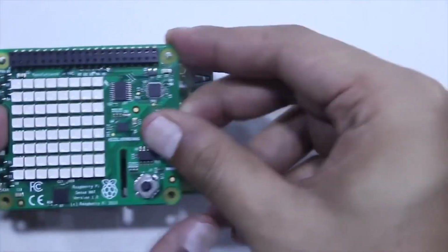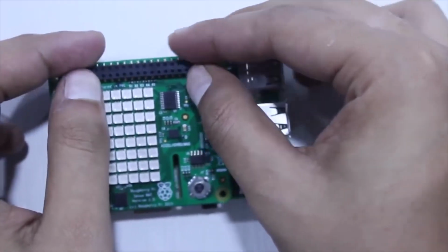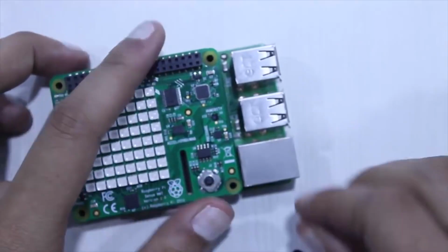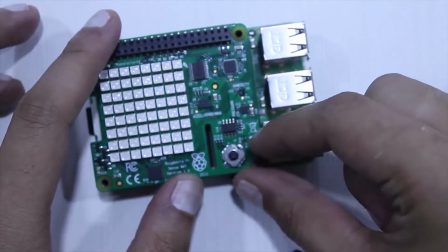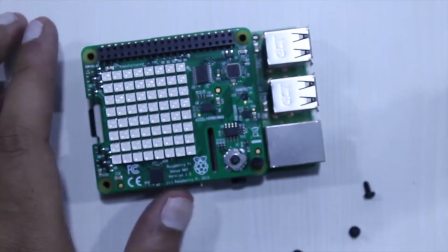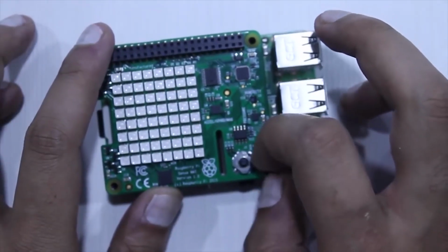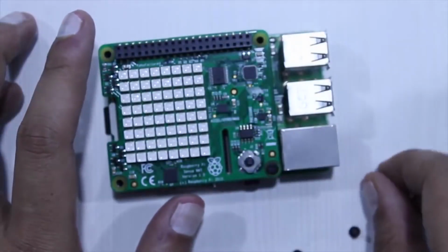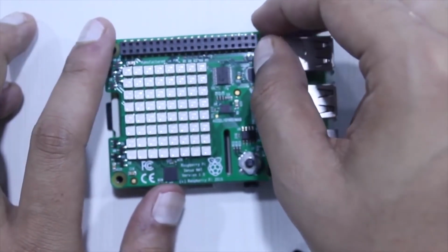Now, it simply sits on top of the Raspberry Pi. Just make sure the alignment is correct, and once you've done that, push it on top and the pins will merge accordingly. Once you do that, you can place the 4 screws across the different ends and tighten it up. Once you're done with this, you can use the Sense HAT for various purposes. We'll use it to measure the temperature, the pressure, as well as the humidity in this room. It has different sensors present on it and we'll be using them for today's demo.